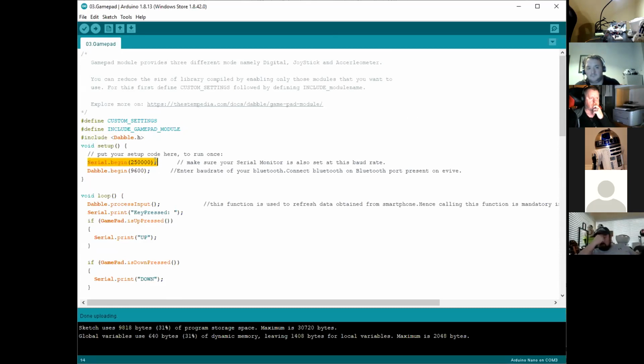This command serial.begin is really important because when you go into serial monitor, which is a way you can see what's going out there, that'll tell you your baud rate, and everybody has different preferences. This one's quite unusual in that the baud rate is 250,000. But when we go into serial monitor, that's quite important. Otherwise, you'll just get gobbledygook out, which I'll talk through.